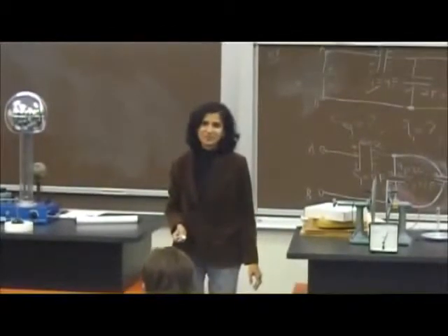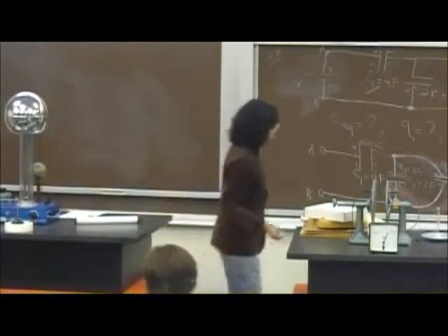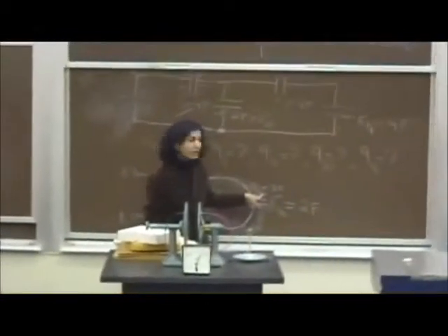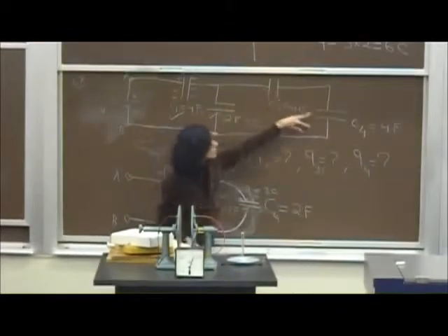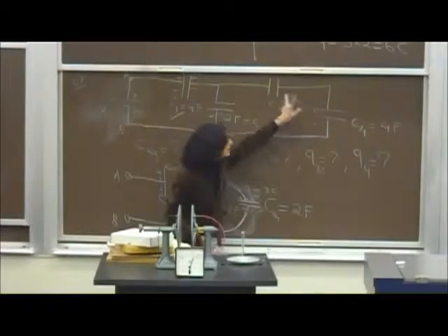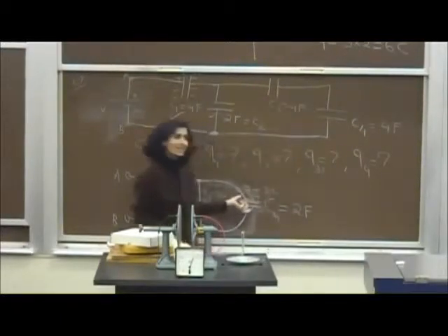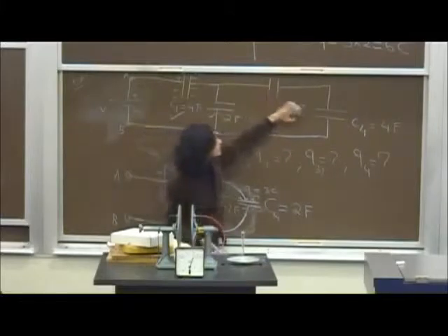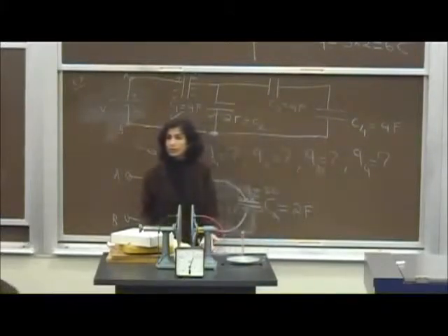Should be the same? It should be, right? So what we are saying is that this is the charge on the equivalent capacitance of 2 capacitors in series, and each of these must have the same charge as its equivalent capacitance, right? Because these are in series. Is that making sense, folks? So that means each of these is also 3 coulomb.